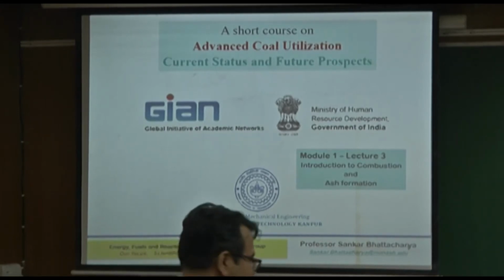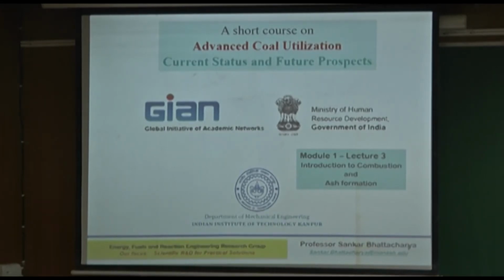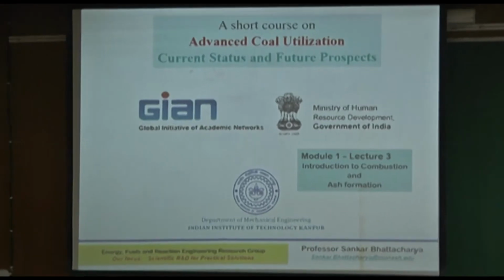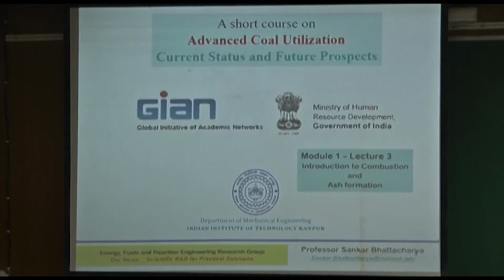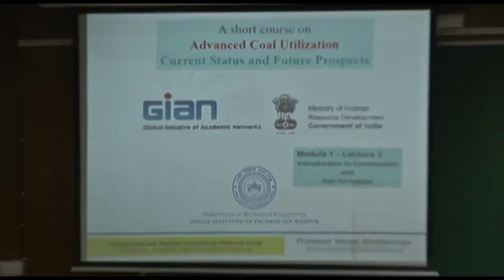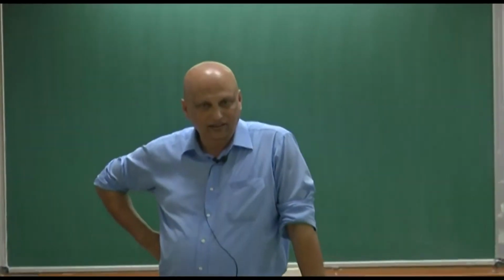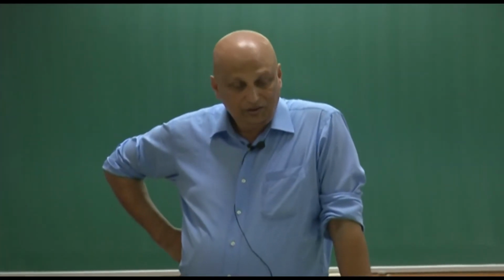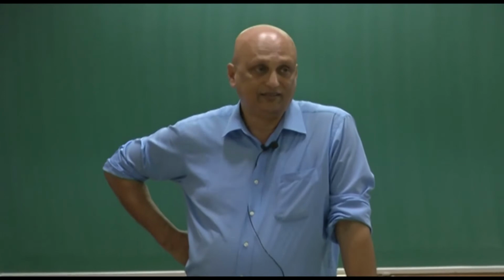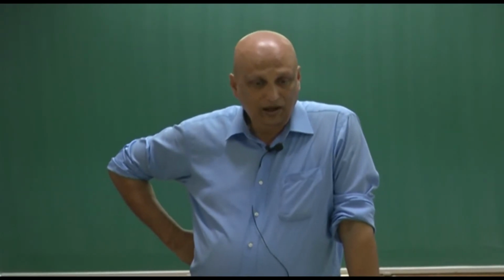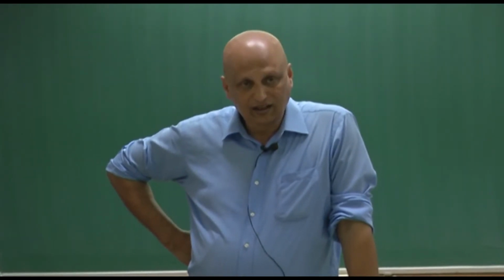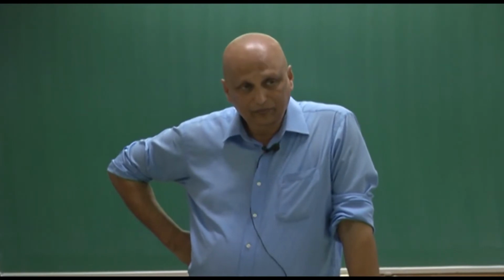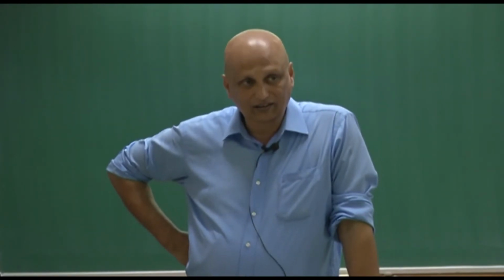Okay, so we have talked about drying, which is the first stage of almost everything, whether you need to do pre-drying in a big separate dryer or a very small dryer right at the front of your gasifier, if gasification is what you are intending. Irrespective of that, drying is needed. So sometimes drying happens inside the boiler, which means in situ drying and then combustion.